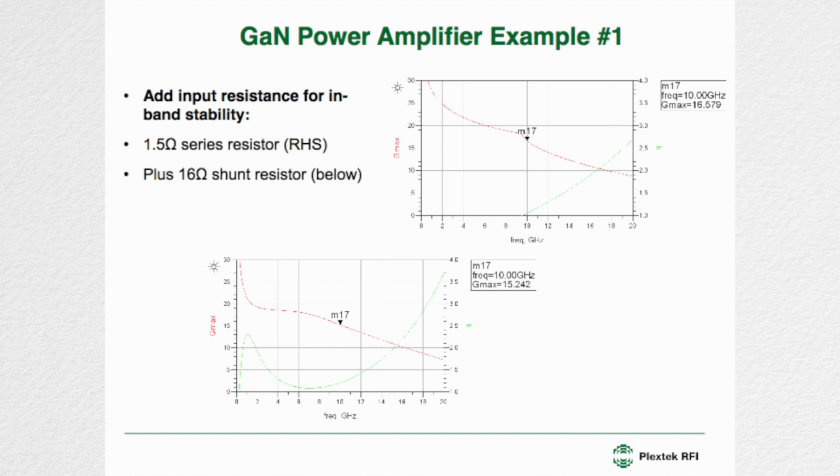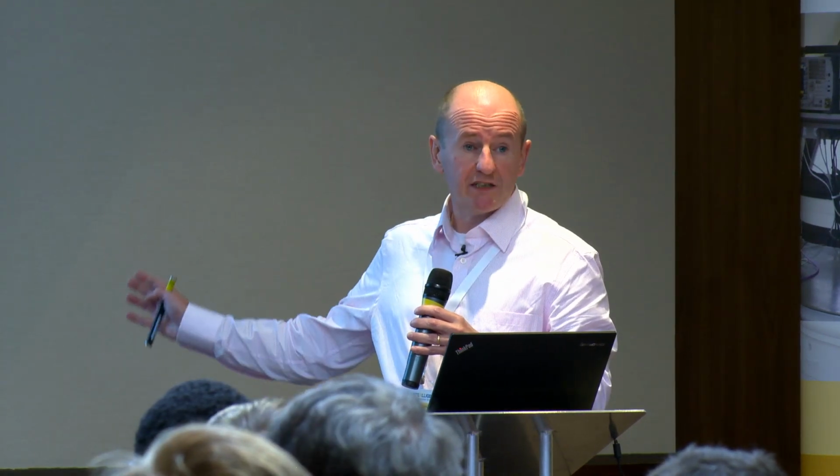Ensuring the low frequency stability in particular, where these transistors have tons of gain, is a vital part of the design process, but it's something we can do later. Similarly, we need to ensure that we have unconditional stability of the complete amplifier to the maximum frequency at which this transistor has some gain.